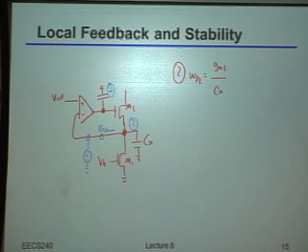Now, by the way, what should that frequency be? Is that like a high frequency, a low frequency? Like, where should that be? It should be high. Why should it be high? GM's large, you mean? Okay, well, let's be a little bit careful. So you're right, it should indeed be high, but it's not just because GM is large. Like, what does this GM over CX kind of remind you of? Or rather, what is that CX probably even coming from in the first place?